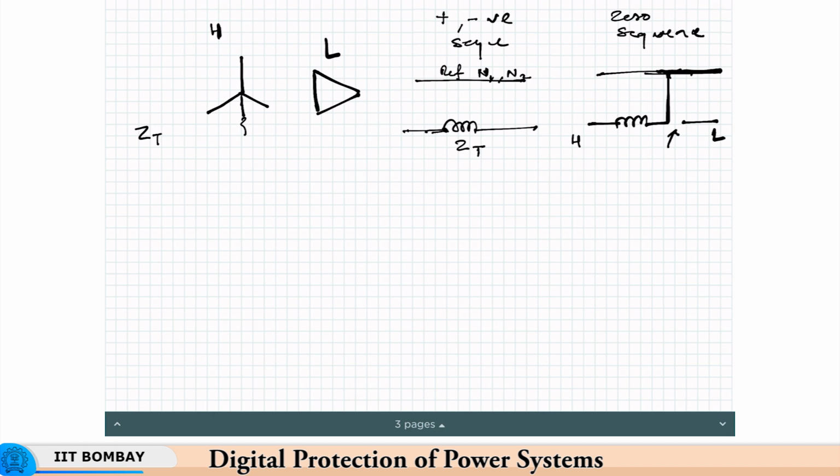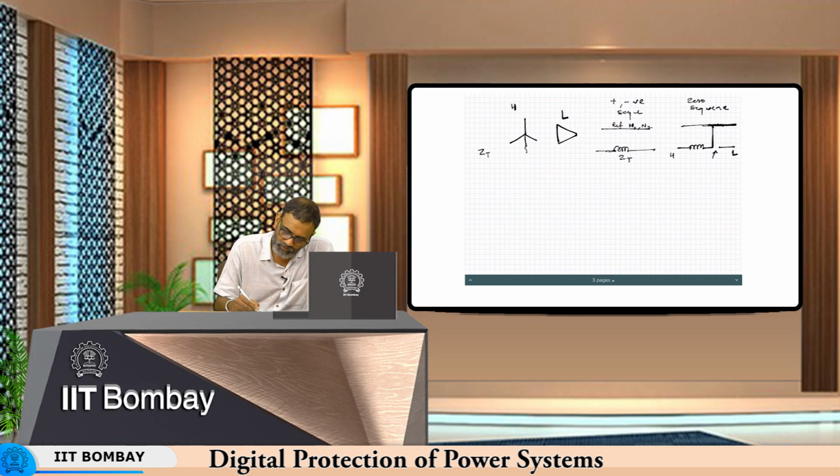However, because the zero sequence current can flow in the limbs of the delta, I0 can flow here, there will be equivalent zero sequence currents flowing in the star side, provided it is grounded, of course. So, that is why this connection here is through. However, note that it is open here, and the delta will isolate everything that is upstream or downstream of that transformer.